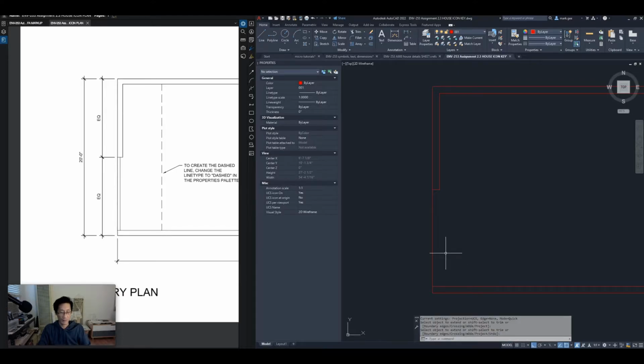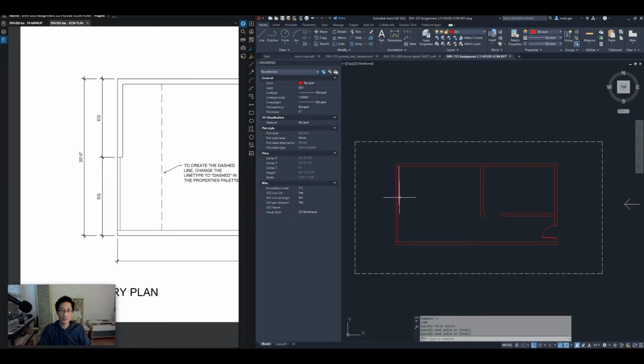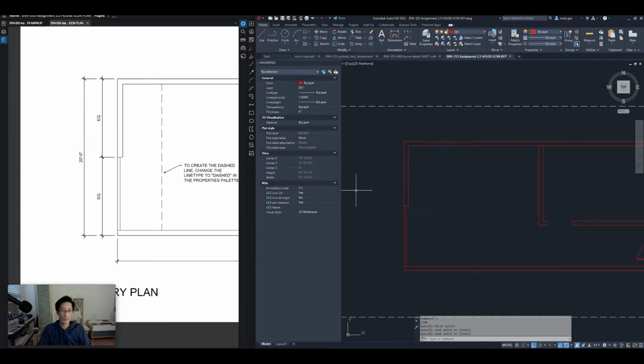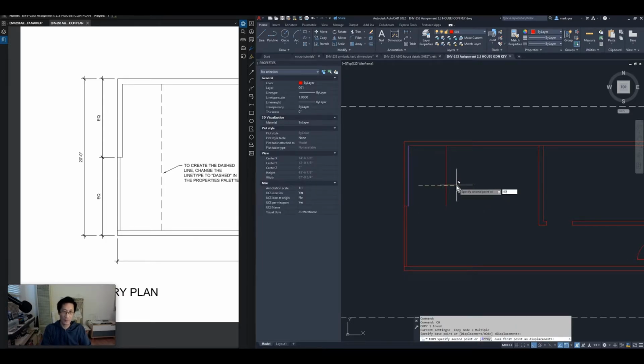And now finally, there is this one line here which represents the frameless glass, and I'll just draw a new line for that. So I'll line up right with that midpoint and snap to the perpendicular here. And so there's that. So that's basically it. Let's see, we have one more thing, which is this dashed line up above, and I didn't put a dimension on there, but I'm just going to take one line here and copy it over 60 inches, because I remember that's what I did when I created the assignment. And I'll use the extend command, EX, and just have that extend to the other wall.